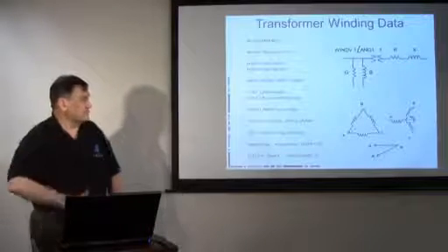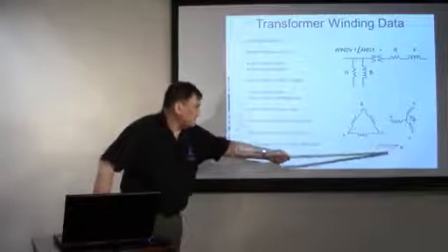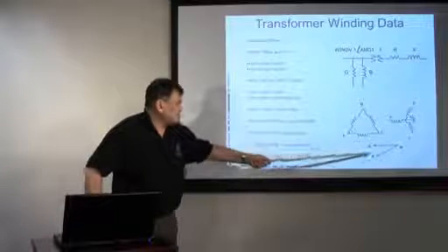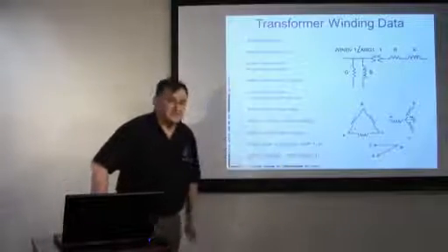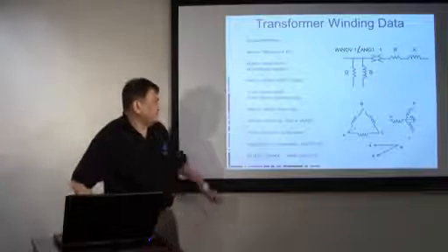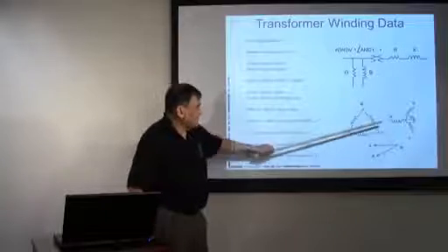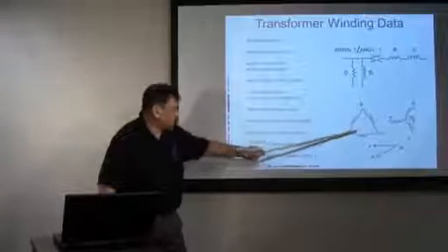You remember that we actually get a phase shift: if this is the voltage on phase A on the delta side, then the voltage for phase A on the star side actually has the shift. That's because in this case phase A is along this winding here, and in this case phase A is literally this vector coming from the midpoint to phase A. So that can be modeled.